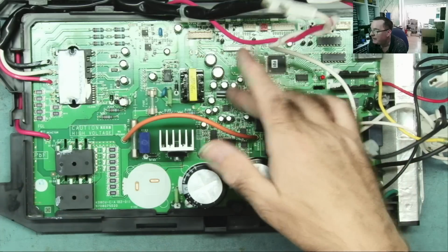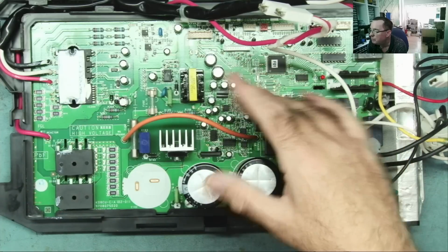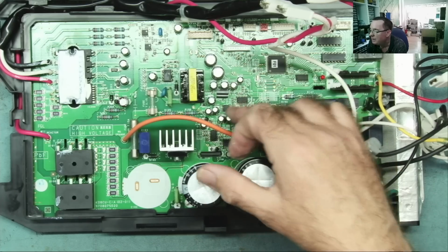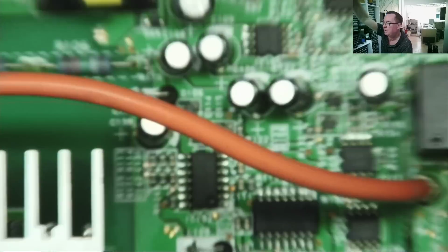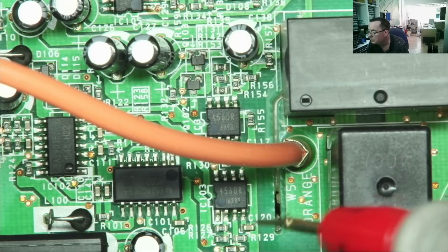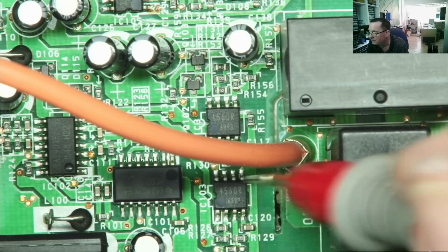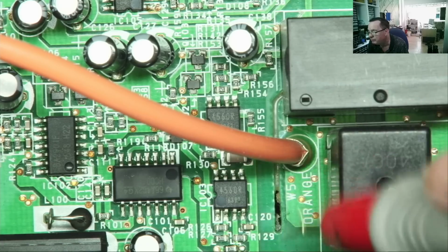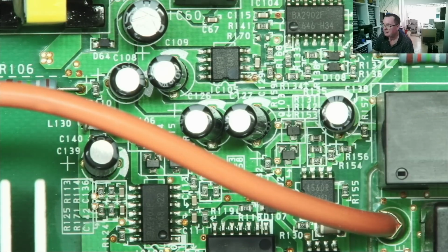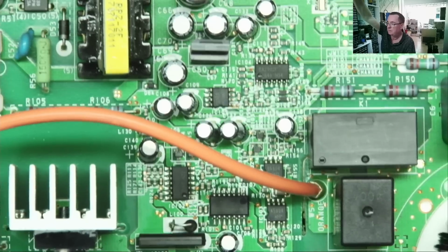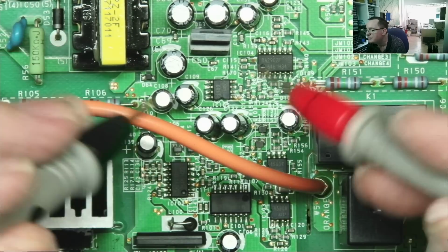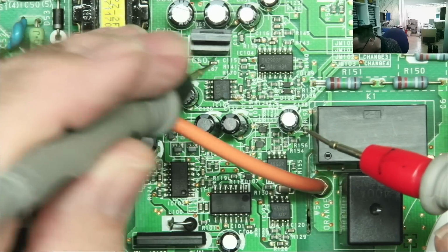We check the 5 volt supply rail. I'm not sure what the other two will be, but there'll be a plus and minus, symmetrical, and ground. We know where ground is, and we know the pinouts for these op amps. So, at least I know the pinout for these op amps because they're common ones. So this should be a negative supply. This should be a positive supply of equal voltage, basically. Ground, let me just find the regulator again, and yeah, it's up there. So, assuming it's not an isolated ground from this ground, but I don't really see why it particularly would be.